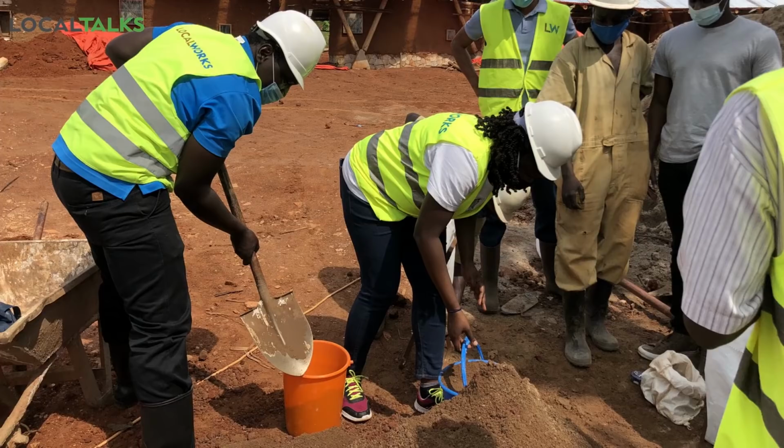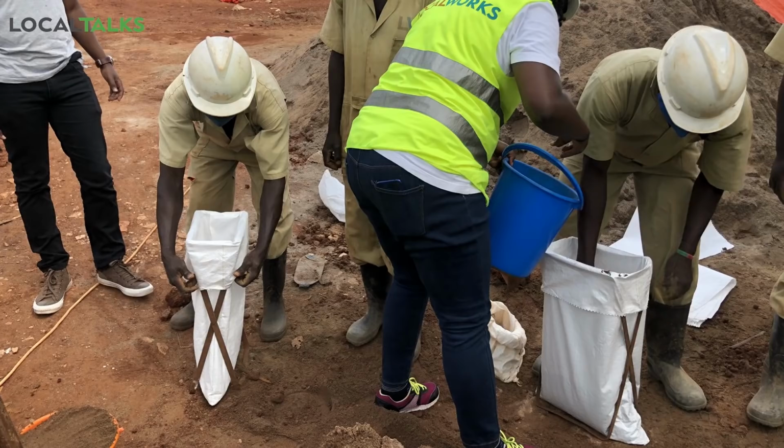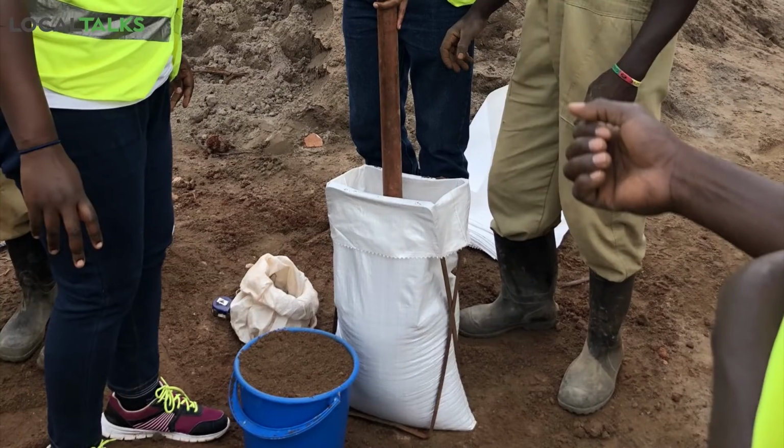Maybe Edson can also talk more about that. Basically, what we already talked about, the optimum moisture content is if you roll a proper ball, with some energy, and you drop it from about a meter. If it shatters so much, then you actually don't have much moisture.